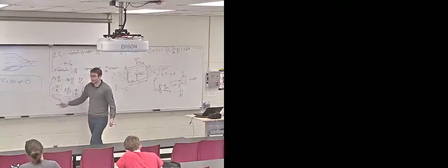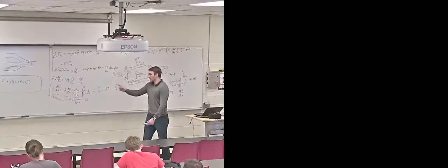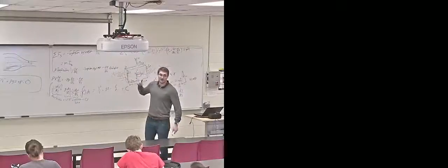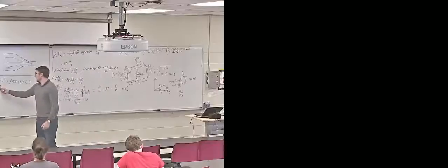This is what allows us to say why planes fly, why propellers work, why rudders work. And essentially, at its core, it is conservation of linear momentum. It's F equals ma applied along a streamline. We already know that these fluid particles in steady flow are following the streamline. So at a point on the streamline, let's figure out what forces are acting on those fluid particles, figure out how much they make those particles accelerate, and group all those terms together. What falls out is this, where we have velocity, we have a gravitational component, rho gz, and we have a pressure component.